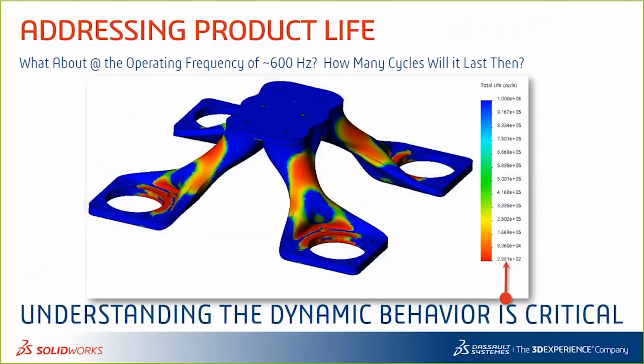What about at operating frequency of 600 hertz? When it comes to fatigue analysis, we can include frequency as well as static analysis as a combination, as a multi-load analysis, to see how many cycles it will be able to withstand. You can see here this number went down a little bit to now 288 cycles. So that's relatively low.